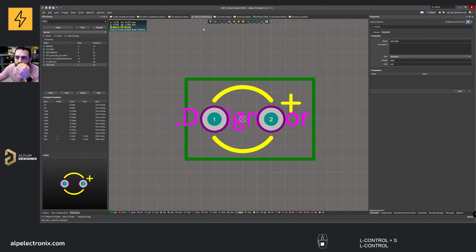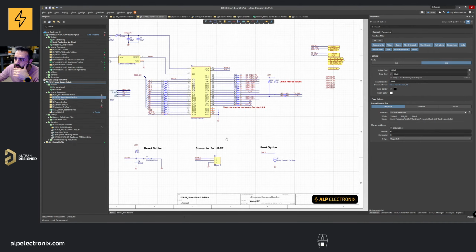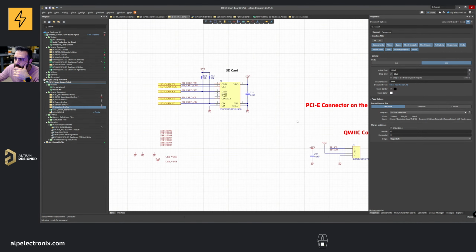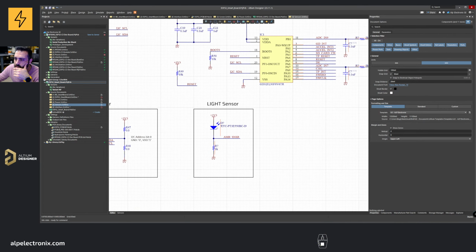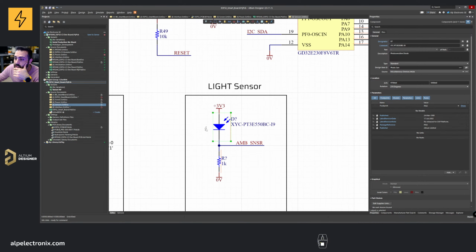Yes. So we need to use this footprint, and then I have created it as LED 3mm, and then I need to select it. Where is the interface? It was in the sensors. So I need to go here, but I need to check first actually if the pins are matching, because it says that plus, the anode, is the second pin, this one, the cathode is this one. Usually there can be some conflicts, and then you can connect in the wrong way. So that's why you need to check these connections always first.